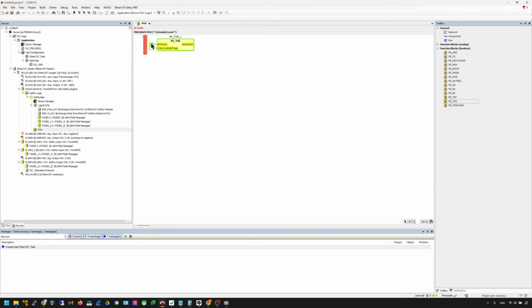So it's very great. Here, the operation is actually the same as the timer that you play with in IEC 61131. So here, I will just call the input SDI as ID10 channel 1. Then I'll give this a 3 second delay. Then I would like to output some signal. How to edit? You just select here, right click, and insert assignment. Then you can select the variables you want to output here. I would like to output this signal back to my normal Codesys PLC.